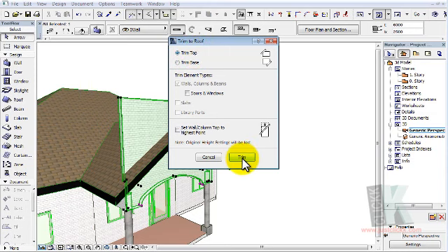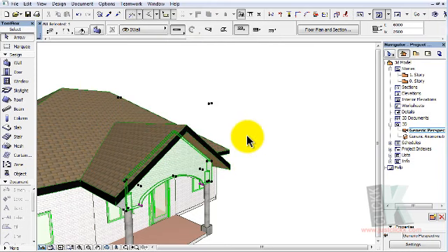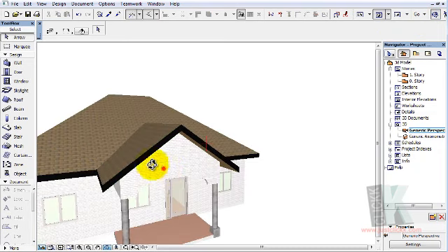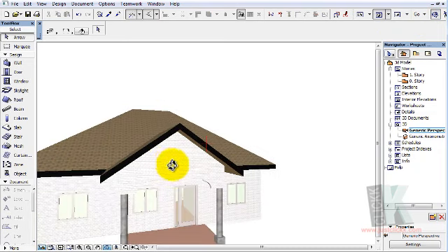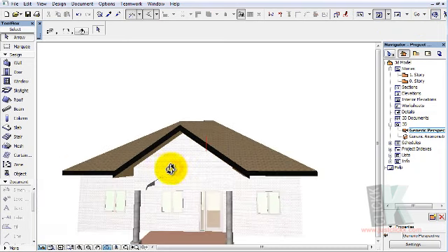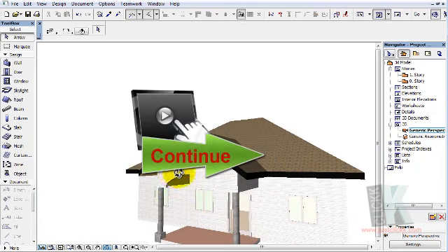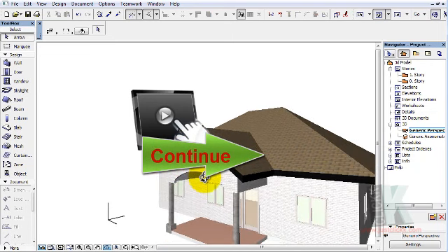And then you click on trim. This now trims that wall to the roof, which solves that problem. So now you can see that everything is cleaned up, well trimmed. So this is how you can achieve your hip and gable roof within a few minutes.